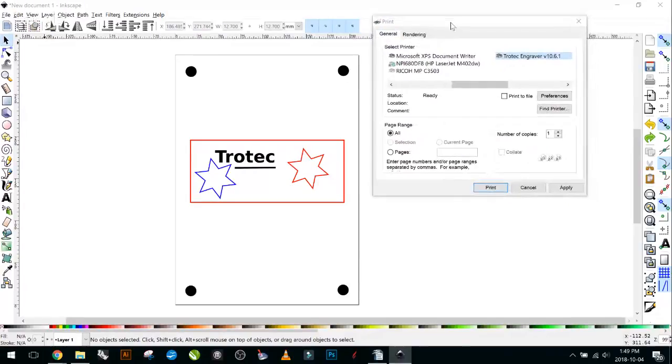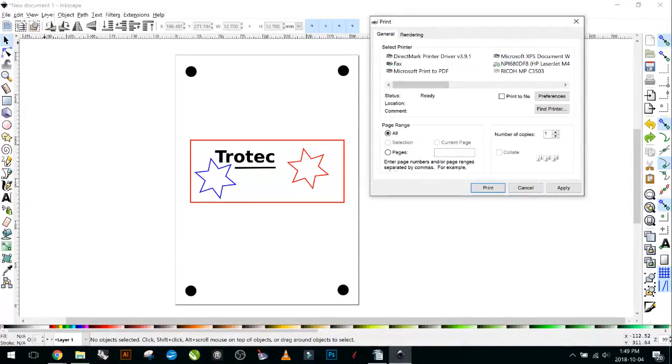So typically, when you're printing, you'll have another section up here that'll say layout, and that might be the reason why when you're sending your minimize the job size or selection to your laser, it's sending a full page rather than just your selection. If you go into the layout tab, there should be options for you to print the whole page, or print from the center of the page only. There's many different options. Sometimes if you move your scroll wheel by accident, those check marks in those boxes get selected, and it's happened to me before where I'm sending things to the laser.